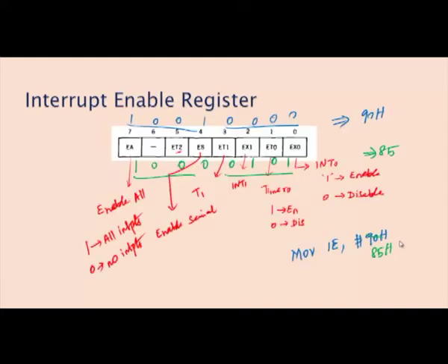The interrupt enable also allows bit access. So, you can give it directly, suppose you want to activate all the interrupts means SETB IE.7. So, what does it represent? This 8th bit is set as 1.